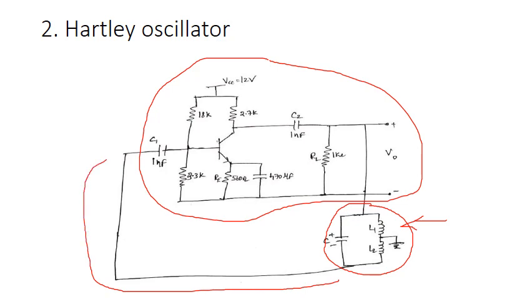signals fed from this feedback circuit. The frequency of oscillation F is equal to 1 upon 2 pi square root of L total into C. This L total and C are from the tank circuit. This is the tank circuit. So L total is the series combination of the two inductors, L1 plus L2.